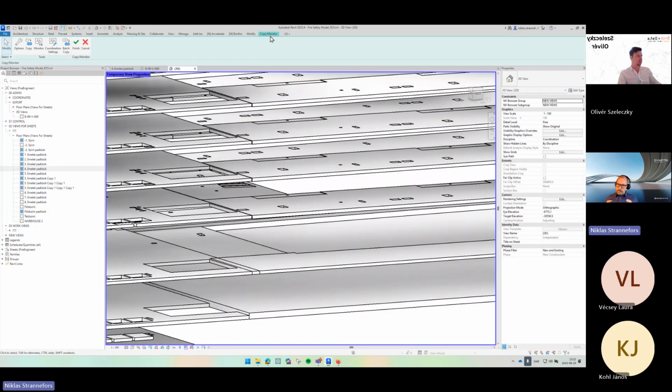I have already prepared the model with different floors for each and every one of the categories that are mostly used. The issue with floors is that the thickness of the floors is set on type, meaning we need to have one type for every floor thickness. So we could duplicate the existing ones to several ones, so we have the same material and same coarse fill pattern.